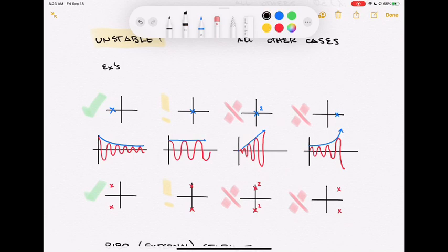What I've done in this particular case is I've gone ahead and drawn some pole plots, some plots that plot out the characteristic roots of our system. So I have an entire row up on top that shows some first order systems, so single pole, except for the third column. That's where I'm going to do some doubling. And these ones are all real, so maybe it would have been more correct just to say that I have all real roots on this top row. On the bottom row, I'm going to look at some conjugate pairs. And we know that when we get some imaginary part of our lambdas, now we're going to get some oscillation, right? Because e to the j something t has an oscillatory component.